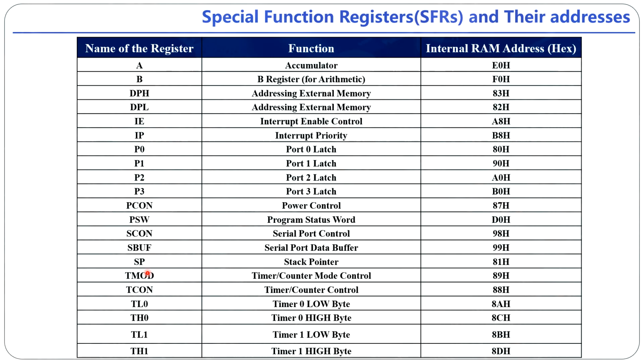Understood? Next register is SP register, that is the stack pointer. The location of this register is 81H. Remember? Next register is TMOD register, that is the timer counter mode control.